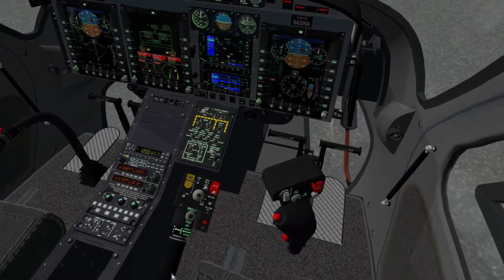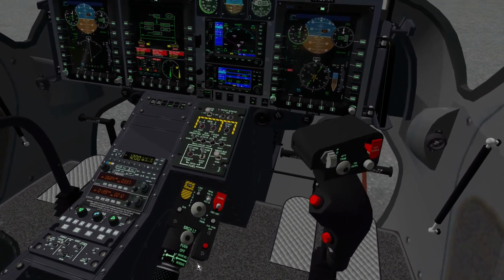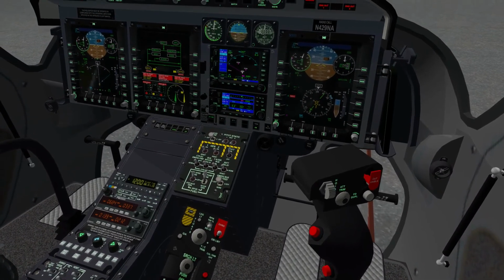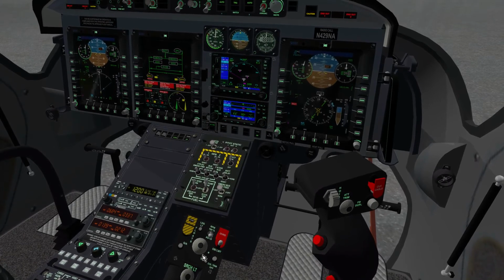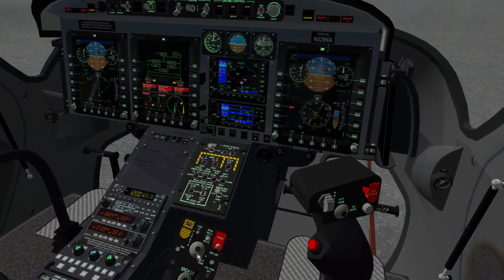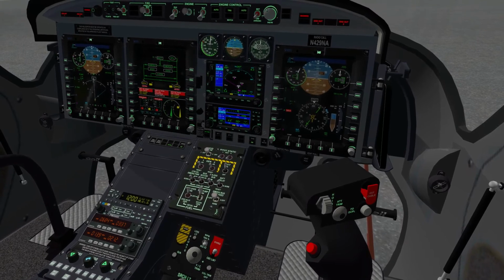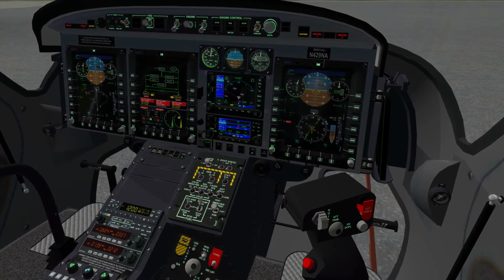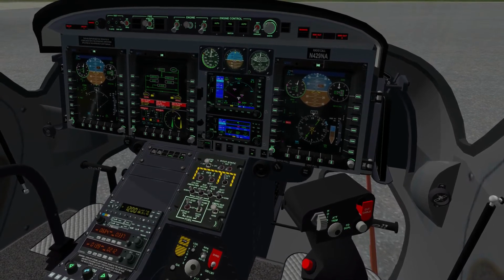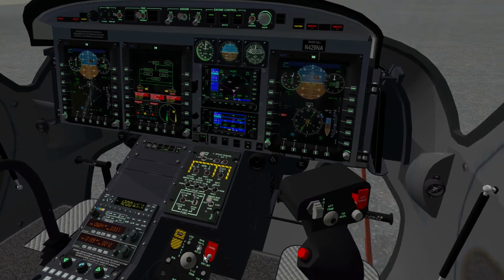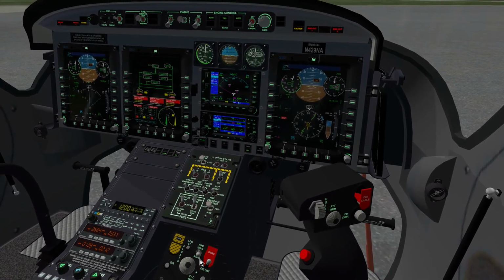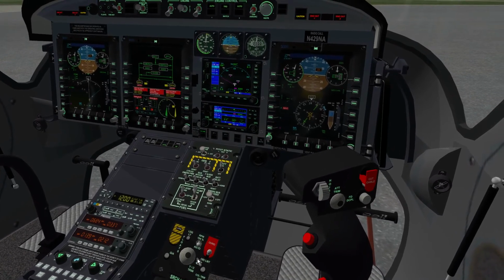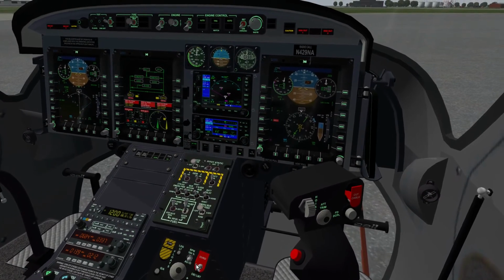On the collective, the searchlight, left right, on. Again here we have the YC trim. This is to do with the autopilot. Left and right increases, decreases selected speed. Up and down increases vertical speed. Landing light, RPM 104 auto used when taking off at max loads, and we set to 104 for hovering and landing.